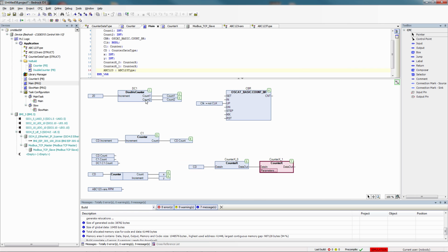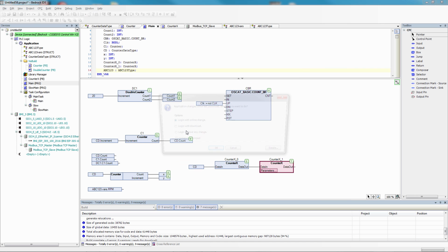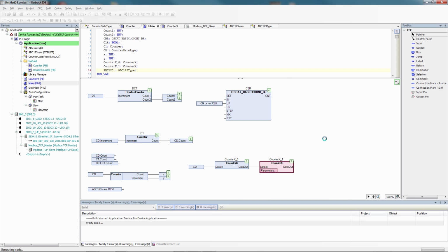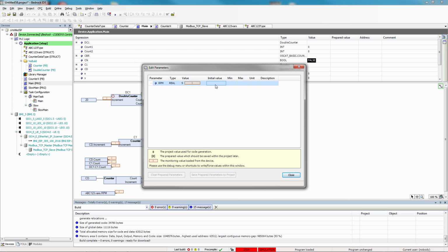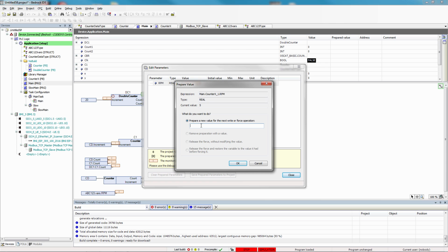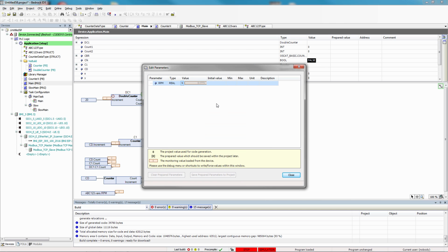Okay. Now we go online with this, and say we've set our parameters for our PID loop at what we think they might be. So now we're online and we're going to tune our PID. So let's say 5 didn't give us exactly what we wanted, so we're going to try a value of 6 instead. All right, and we're going to do the old Control F7 to write that. So now we're actually running our plant with the value of 6.